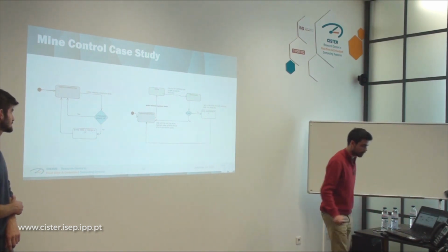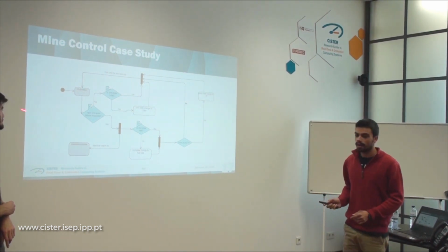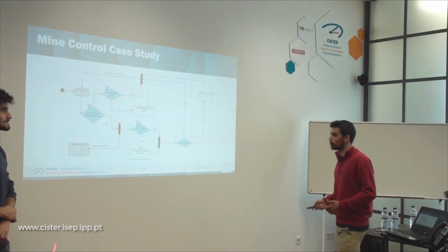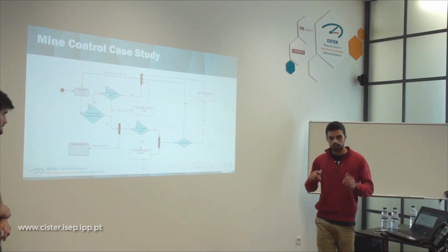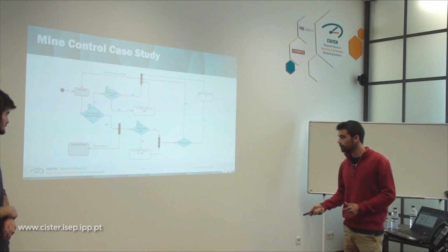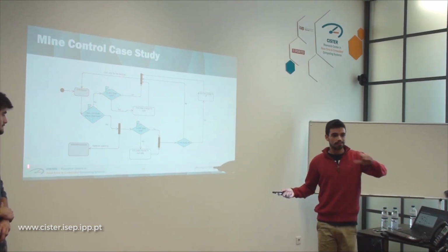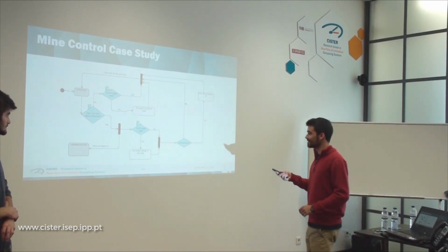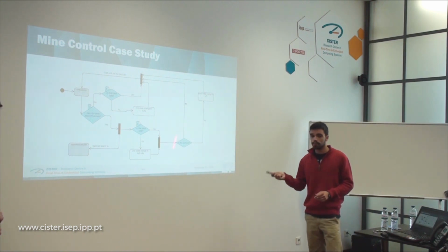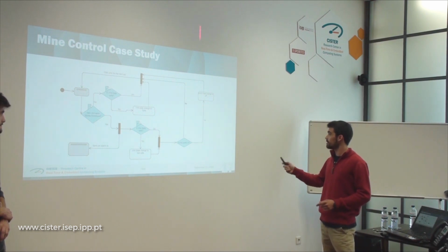And then here we have our situation to turn off the pump when the methane level reading is explosive, above the threshold. Here the CH4 sensor will simulate our reading. If the methane level is above the threshold, we send our alarm to the operator, then check the present state and verify if the pump is on. If the pump is on, we change the state of the pump.